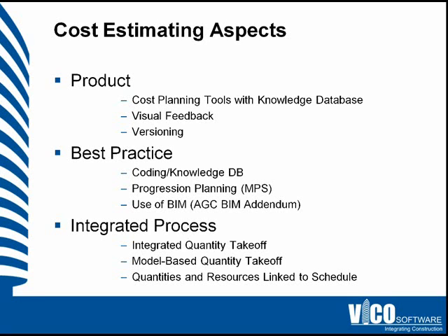Also, to look at downstream integration, the quantities and resources that Jim calculates in his estimate are not used in a schedule. So the resource loading that happens later on in the schedule plan is not coordinated with the numbers in the estimate, which may lead to discrepancies.